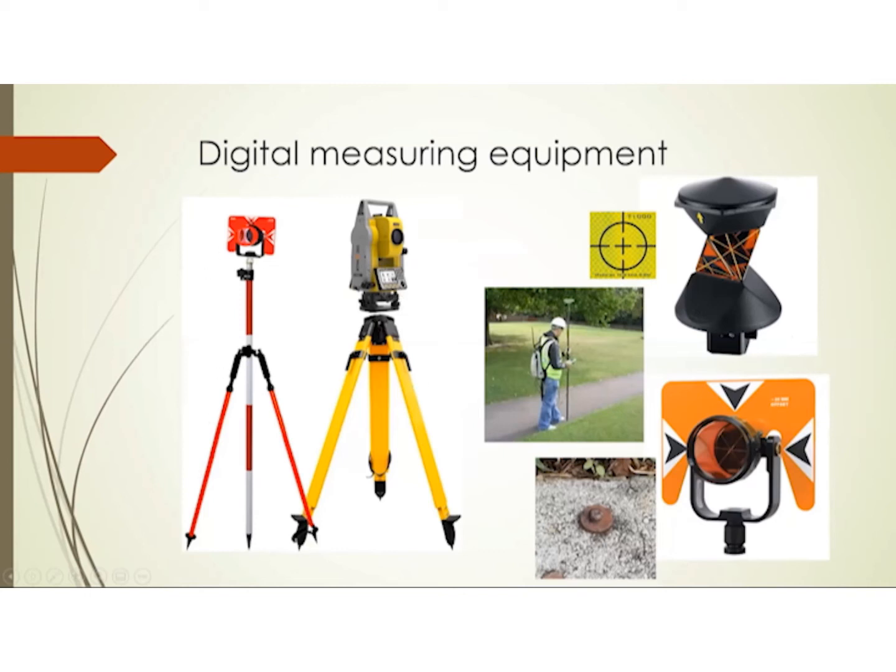So you place a tripod with a prism, this prism here, above a nail or a control point, a known point, possibly capturing that known point also with a GPS location device, and then record points in the logger by noting that the laser is pointing, or the viewfinder is pointing, at maybe the top of a tree, or four window corners, or the edge of a path, whatever is being recorded and tagged and logged to be measured.